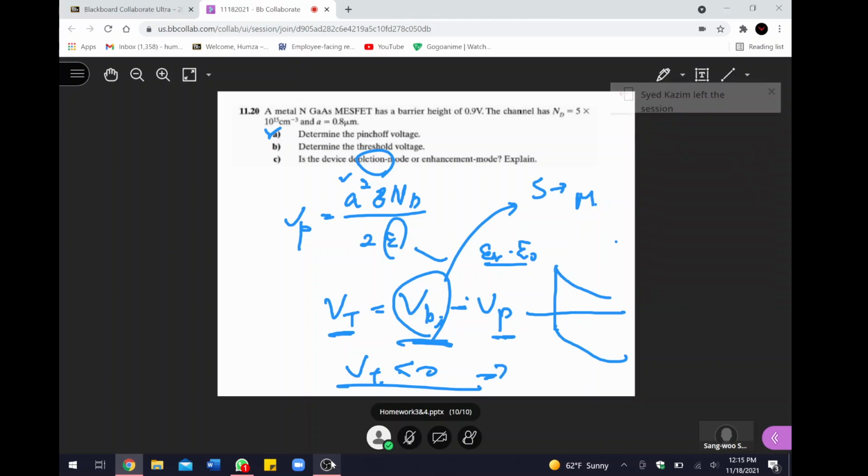So on the metal side, as we define, there is a barrier height. On the semiconductor side, this is q VBI. This one you need to calculate: the barrier height minus the difference EC minus EF for the given doping, right? Okay, I see.